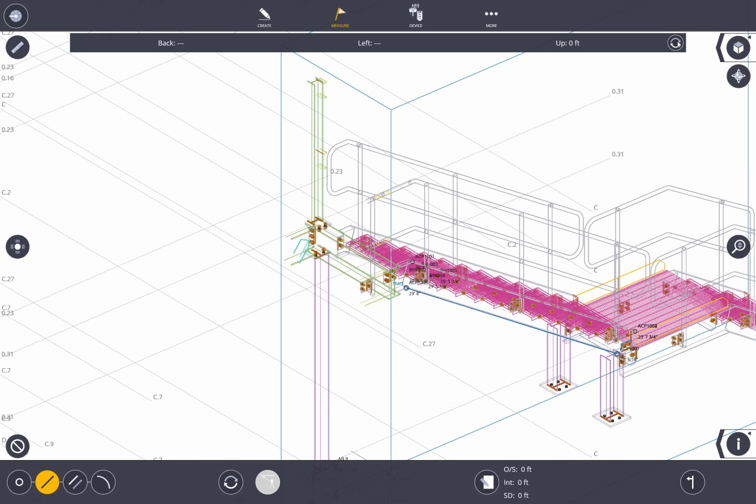Typically, if I'm staking along that line, using a down from the start point and out or offset left or right to show me where I am when I'm staking those individual lines. You can also stake out curves or transfer some of those points from the floor to the ceiling as well.